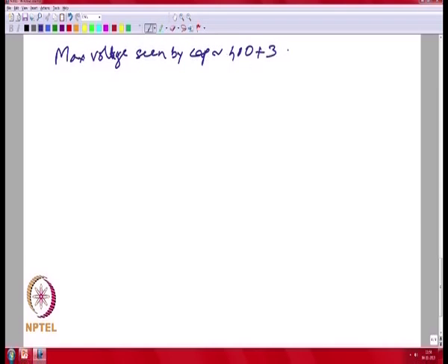You have 33 volts because of your 50 hertz effect. You have about 6.6 volts because of your 100 hertz effect. So, you have about 440 volts seen on your individual capacitor bank. So, you have actually a very tight margin of just 10 volts. So, your control has to be very effective so that you do not have large overshoots when you are dynamically controlling the DC bus.